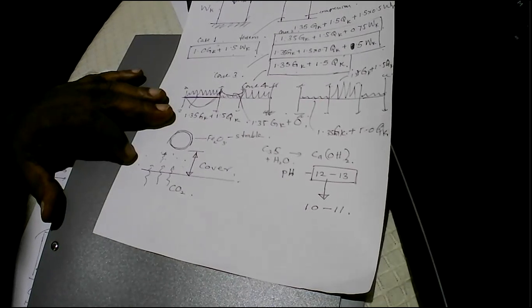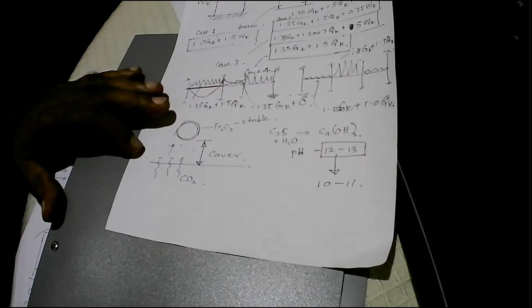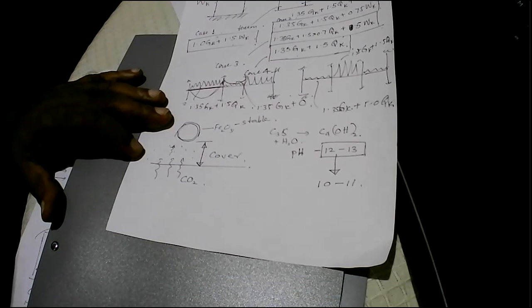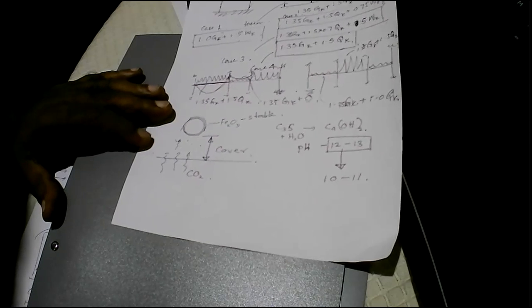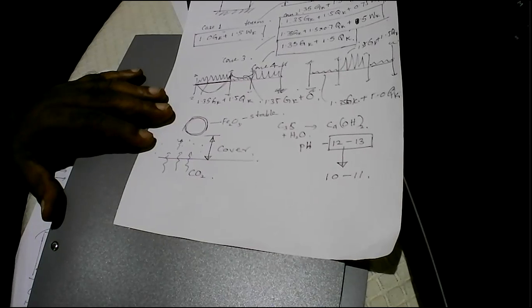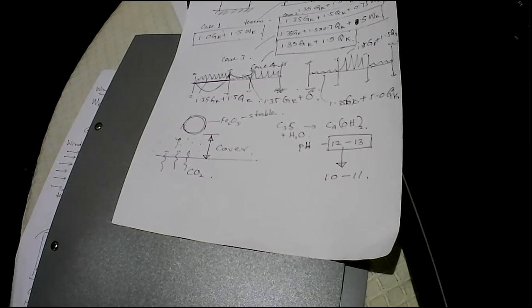It deteriorates. So real corrosion can start around the reinforcement, and that can lead to rapid deterioration of reinforced concrete. So to prevent this, we need to have adequate cover for the reinforcement.